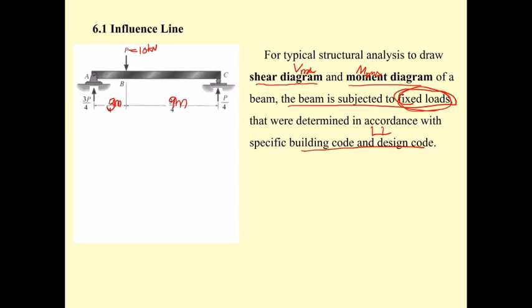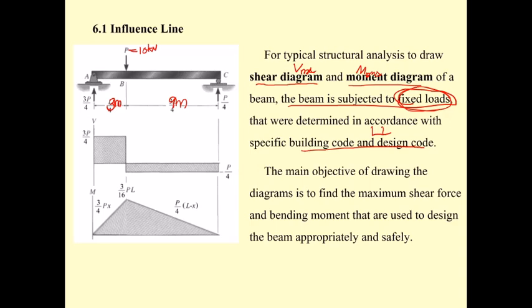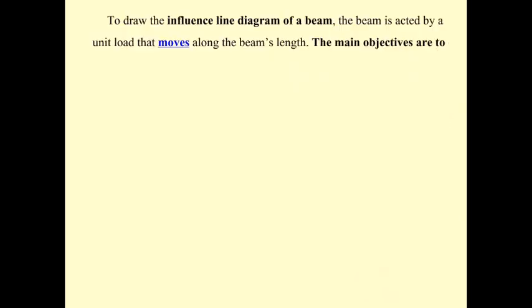The live load is going to be different from a beam in a university building, right? Anyway, if you may recall, when you get the Mmax and Vmax, you can design the section of the beam as it shows here. The section may be rectangular or a structural steel section, those kinds of things.